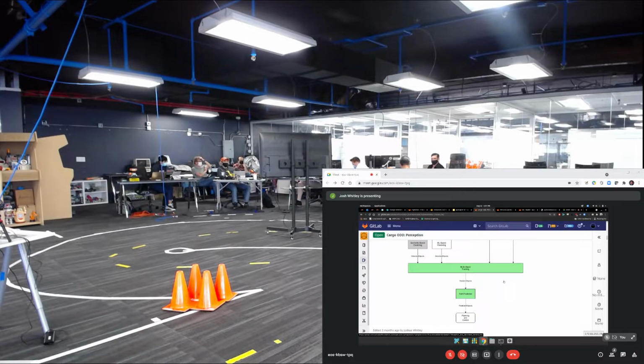Yeah, radar, every sensor has failure modes, and radar helps cover some of the failure modes of camera and LiDAR. So radar is able to see through things like snow and rain and fog, and cameras and LiDARs usually can't do that. So you get kind of a safety fallback. Also, radars are better at velocity and acceleration detection, because they use the Doppler effect to measure the movement of the object. That's part of the technology. This is how it works. And LiDARs don't do that. They're time of flight based, right?